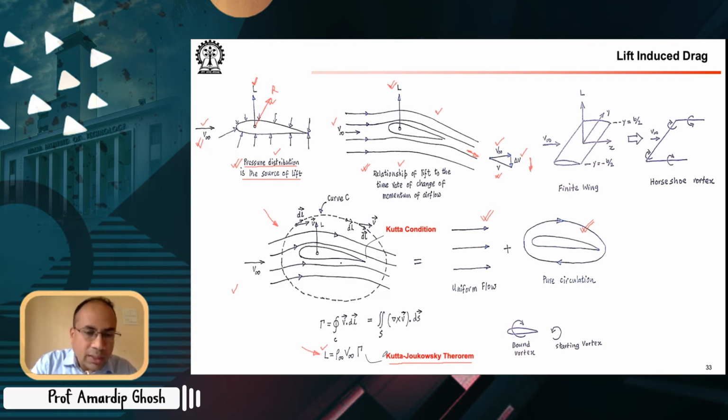It can be shown that lift on that rotating circular cylinder is something like rho infinity V infinity times the circulation. And it can be further shown that through suitable transformations, the same lift is actually generated for cylinders whose cross sections are not circular. Okay, so first we show that for a circular cylinder, lift is equal to rho infinity, V infinity, and circulation.